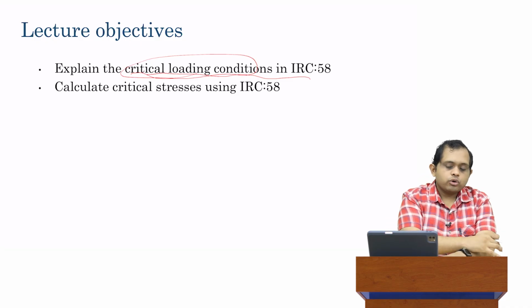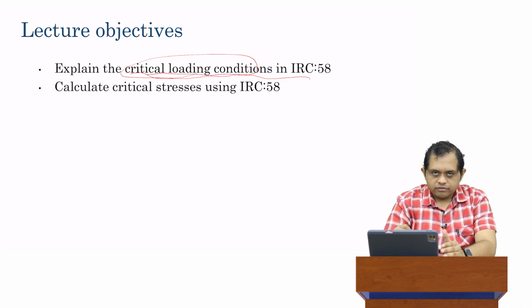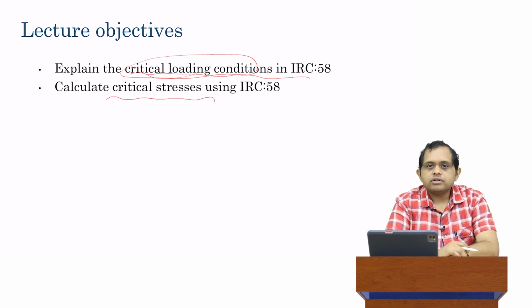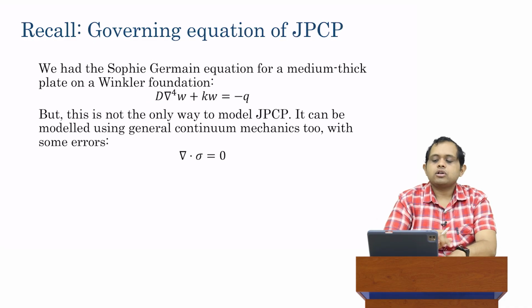So in today's lecture, I'm going to look at critical loading conditions. And then I'm going to show you, after looking at critical loading conditions, how stresses are calculated. We'll actually do an example. The example we'll actually do in the next lecture, but I'll show you this critical stress calculation model in IRC 58. Okay.